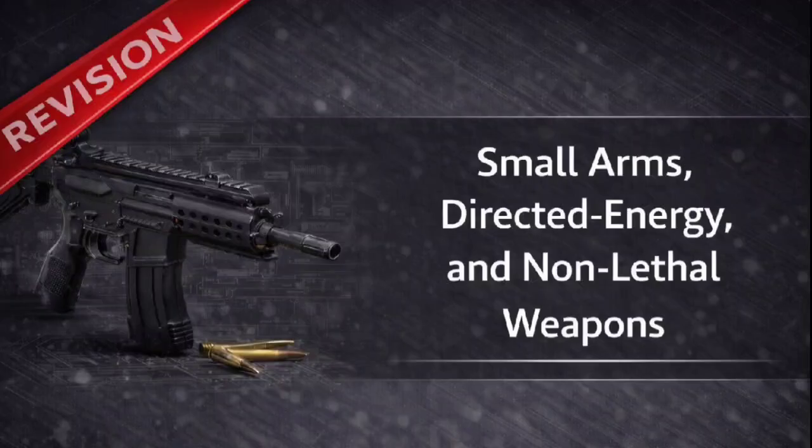First, the physical displacement of the weapon's center of gravity from the central axis of the bore. Second, the displacement of the butt from the bore axis. And third, the rotation of the firer about their hip, caused by that intense backward force transferring momentum to their entire body. And when you're firing automatically, this cumulative effect is devastatingly visible. It's called muzzle jump.